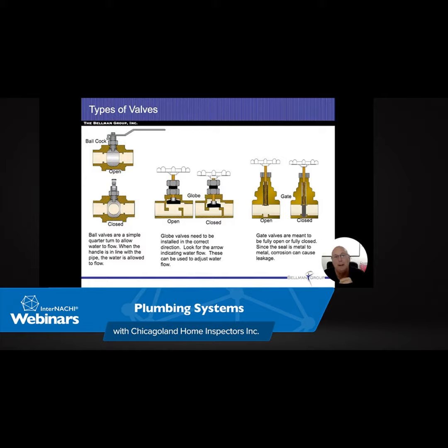And if we don't let the air flow and we're not vented, then we're going to start siphoning. That air is going to come into those pipes. It's going to come in from somewhere. If it can't come in from the roof, it's going to come from our traps that are in our plumbing pipes, and we're going to siphon those out, and again, sewer gas is going to start entering our building.